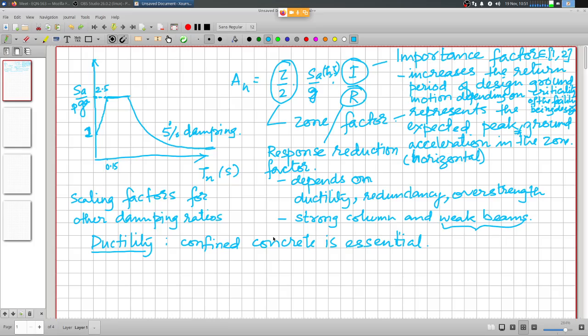And of course, another side effect of using very closely spaced lateral ties: our intention is to have the confining effect on the concrete, but another side effect that we get is an increase of shear strength. Shear capacities are increased because those lateral ties help us in withstanding shear. So any chance of failure in shear is automatically eliminated.